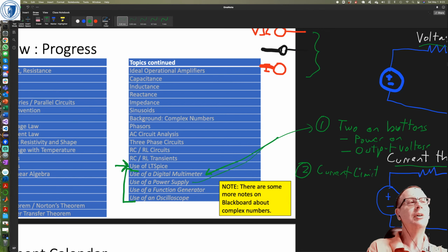Sometimes that current limit gets set to 0. So you'll turn it on, and without the output voltage on, you can set what the output voltage is, and then you turn the output voltage on, and the voltage you get out of it is 0. That's sort of a safety feature, it's actually so that you can try and approximate a constant current source.